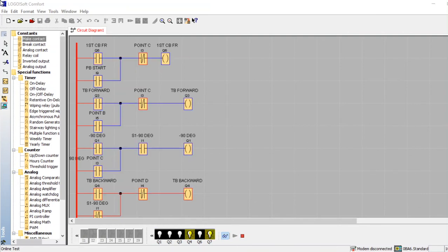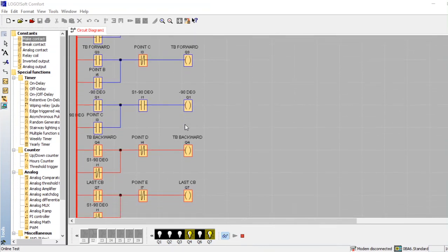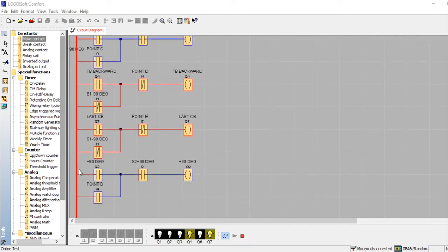I3 is on. Q4 is on. Q1 is on. Q7 is on. Observe when we get to I4. You see, when we get to I4, Q4, Q2 are off, Q7 is remaining, and it gets deactivated when we get to I7. And the program indeed is complete.